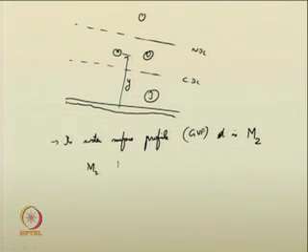Like this you determine the various flow profiles. Or if you are given the water surface data, from that you can easily identify whether it is in zone 2, whether it is an M2 profile, or an M1 profile, or an S2 profile, like that.